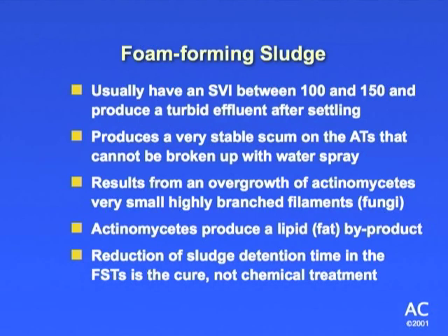So it's just something to think about, that when you have these problems, your population's changing a little bit, and something's caused it to change. So you've got to stop and think, what's caused that change? Your biggest effector of your plant is your influent, okay? And then, of course, it's what you're doing internally in your plant. So long as you're consistent and providing the neutral pH, in this plant we'd like to see around a 7.2, actually. Good, adequate alkalinity for your process, keep an eye on your alkalinity, and keep an eye on your DO. You're doing what you can do for the home base, okay? And then you just have to deal with what's coming in with your influent.